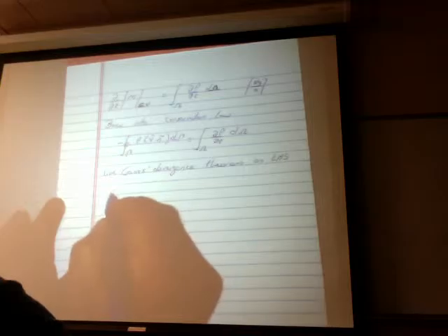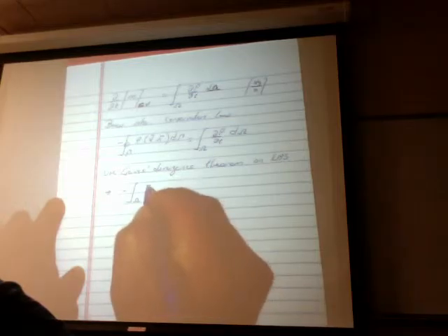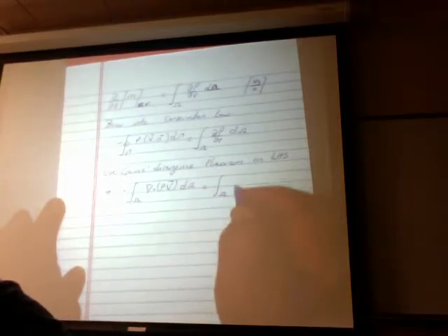On the left-hand side, the Gauss divergence theorem says that we can transform a line integral, or that's a boundary integral, into a domain integral. So we have rho v dot n, which can be transformed into the divergence of rho v, d omega, is equal to the integral of d rho dt, d omega.